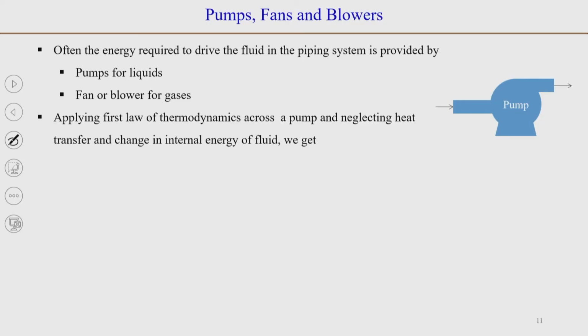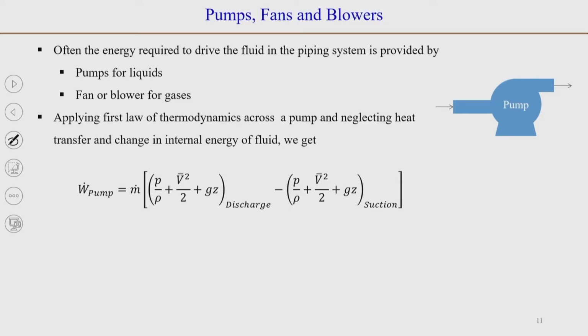So, we could write down again the energy equation. If we write down the energy equation, we had Q dot minus W dot, there was an unsteady term which we will not write here, and then we had the integral of (e plus P by rho) V dot dA.